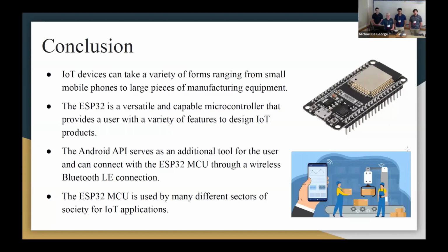How far along are you guys with the hardware design? You mentioned you're going to get the board printed. What kind of tools are you using? Yeah, so right now we're working towards, so that's where part of the legacy project comes in. Our ultimate goal for this semester is to probably breadboard. So we're probably going to try and print a really cheap breakout board so that we can get the chip mounted on a solution so that we can then breadboard a circuit to flash the chip. And hopefully, if the circuit works, we can then put an order for a printed circuit board. That's one of the ultimate goals.